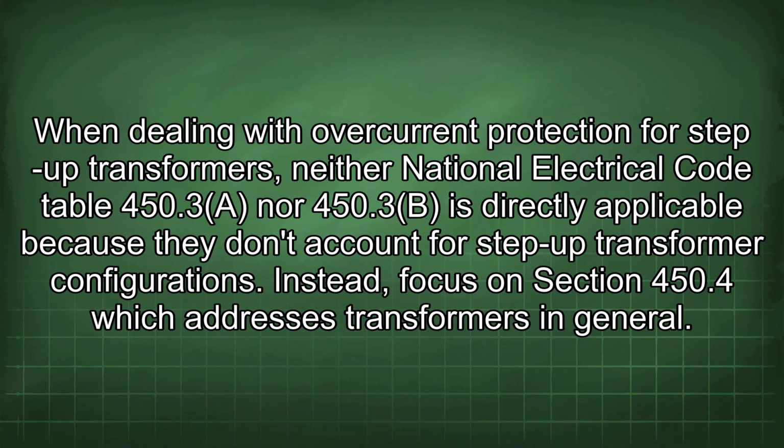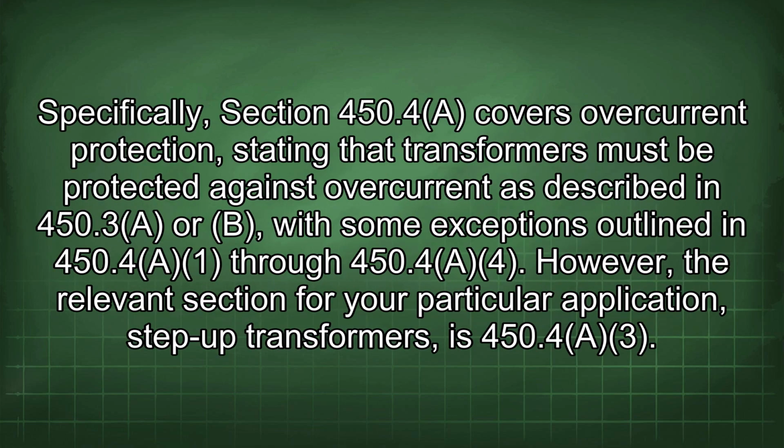When dealing with overcurrent protection for step-up transformers, neither National Electrical Code Table 450.3 nor 450.3(b) is directly applicable because they don't account for step-up transformer configurations. Instead, focus on Section 450.4, which addresses transformers in general. Specifically, Section 450.4 covers overcurrent protection, stating that transformers must be protected against overcurrent as described in 450.3(a) or (b),